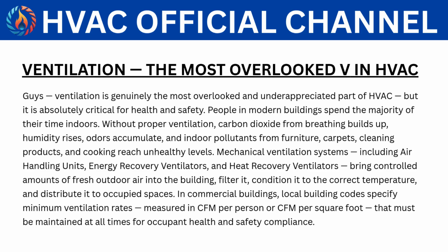Without proper ventilation, carbon dioxide from breathing builds up, humidity rises, odors accumulate, and indoor pollutants from furniture, carpets, cleaning products, and cooking reach unhealthy levels. Mechanical ventilation systems, including air handling units, energy recovery ventilators, and heat recovery ventilators, bring controlled amounts of fresh outdoor air into the building, filter it, condition it to the correct temperature, and distribute it to occupied spaces.